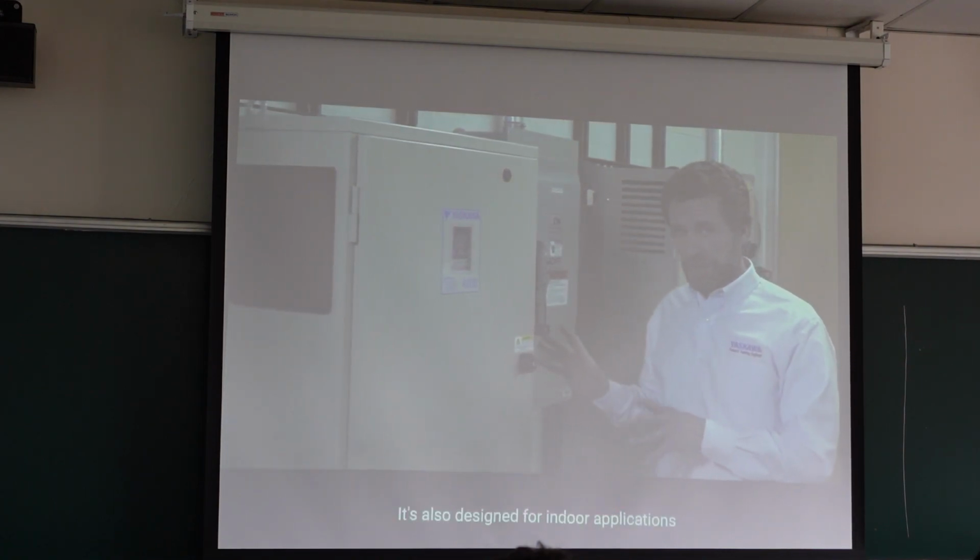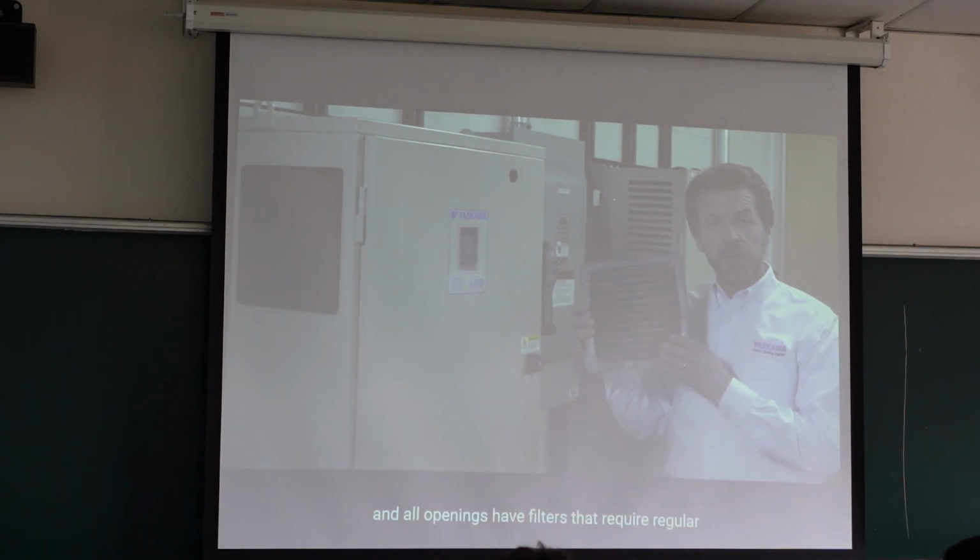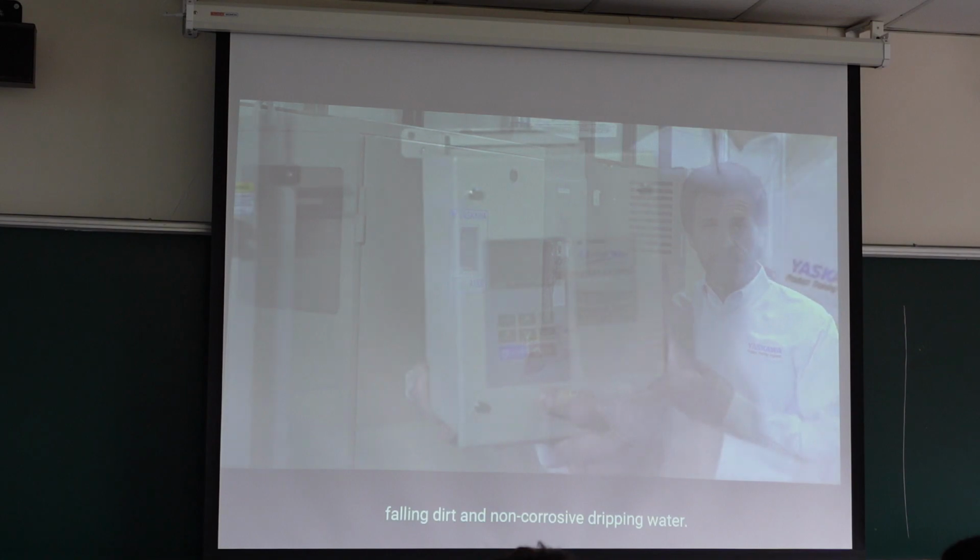NEMA 12 steps up the protection. It's also designed for indoor applications. All openings have filters that require regular maintenance. The filters protect against circulating dust, falling dirt, and non-corrosive dripping water.